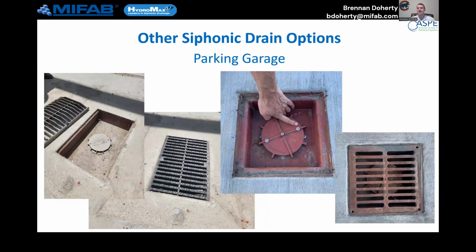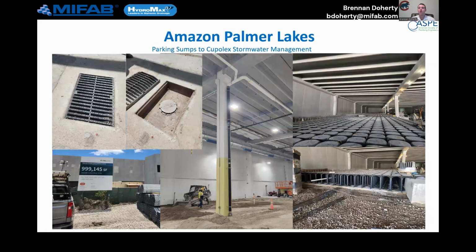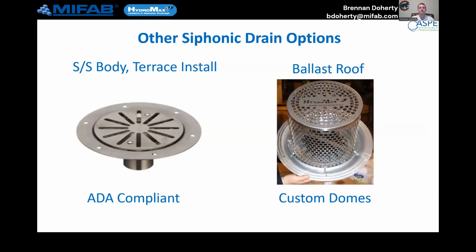Another application is a parking sump. If you have a parking structure, why would you do that? You can collect more drains together, so you have less verticals. It's a smaller diameter pipe, so you have less of an impact through that sidewall, again allowing you to collect more drains in that riser. And number three, you can define where you want that discharge point to be. So if you're using any type of rainwater collection system, you could define where that was within your building rather than having gravity and pitch tell you where it needs to be. This does give you the opportunity to add LEED points to your project.